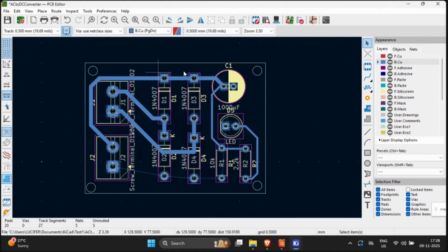We don't want to have the option of having the entire copper removed and only left with traces. What they instead follow is they'll define an outline along each of the traces. They just remove the copper from the outline of the trace so that the rest of the plate isn't conducting. So basically, you can think like they're insulating only the wires. The rest of the plate is copper.